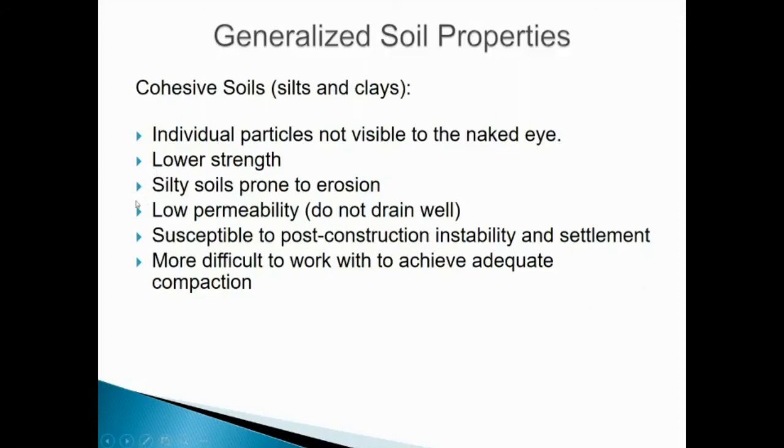Silty soils especially are prone to erosion with rainfall and near flowing water. Silt and clay soils do not drain well, they have low permeability and have a tendency to hold water, which reduces stability. So silt and clay soils are susceptible to post-construction instability and settlement. Because they have a low permeability, they are more difficult to work with to achieve adequate compaction. They are more difficult to uniformly moisture condition.